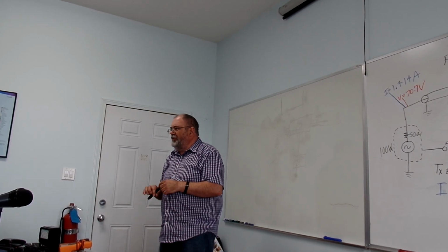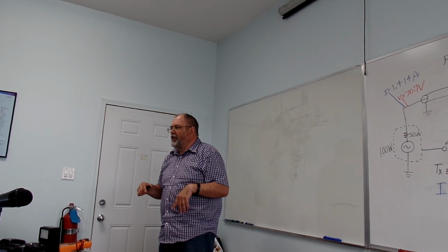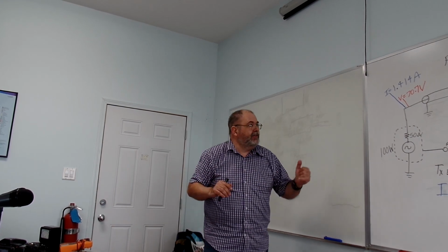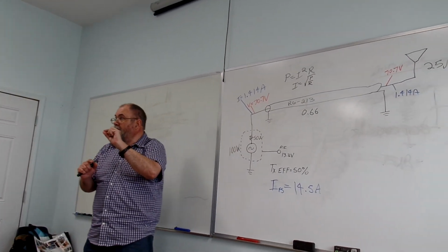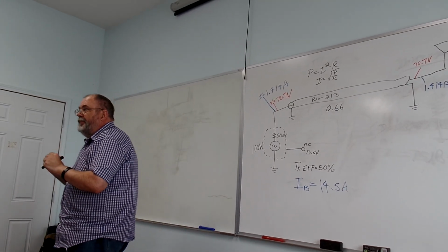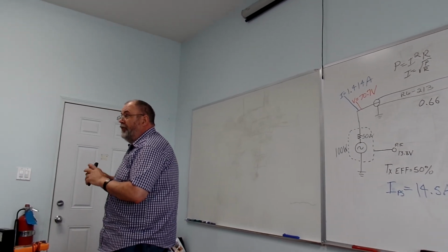There's low loss coaxes out now, like for example the LMR 400s and stuff like that. And really what they do for low loss is for the dielectric, that's the spacer between the center conductor and the shield. If you can make that a vacuum, you have very little loss, because once again, there's no molecules to get in the way. So what they do is they start using plastic materials, but they use a foam material, so they put air bubbles in it. So it's got a lot more air in it and a lot less plastic in it. And because it's got more air and less plastic, the velocity factors will come up to about 0.8, 0.82, 0.85. And when you get up into the large hard lines that are actually air dielectric, their velocity factors are like 0.98 or something. They're real high.